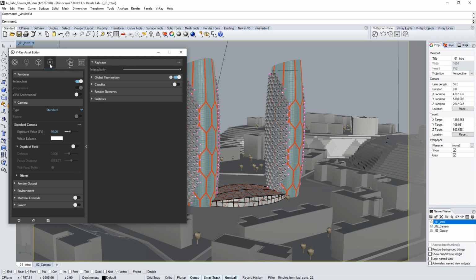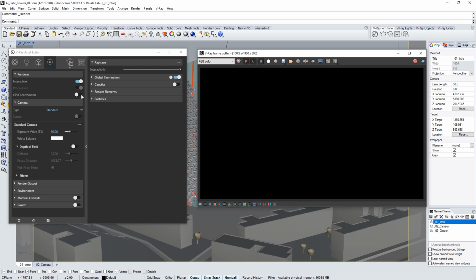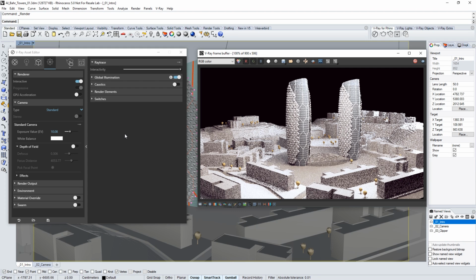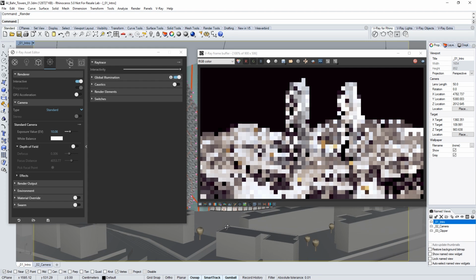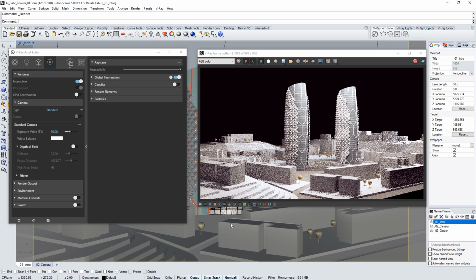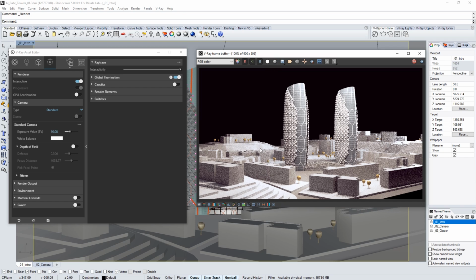By default, the render engine is set to interactive, which means you can start render once, change geometry, render parameters, materials, light condition, etc. and you get instantly a visible feedback from the scene in the render window called VRay Frame Buffer, or VFB. The render will get more and more clear over time. Let's stop the rendering for now.